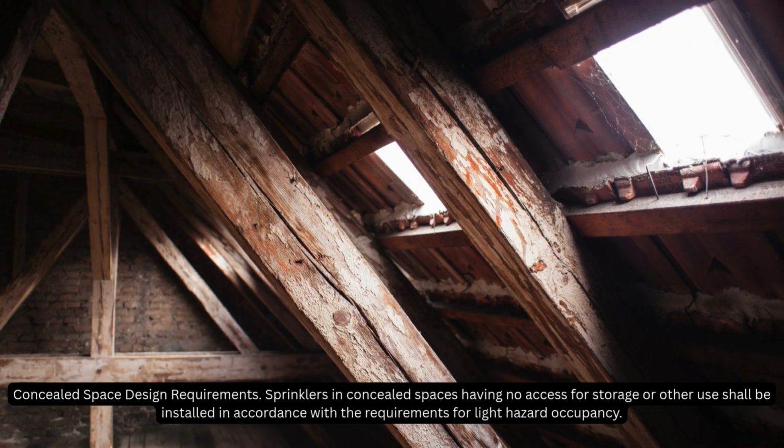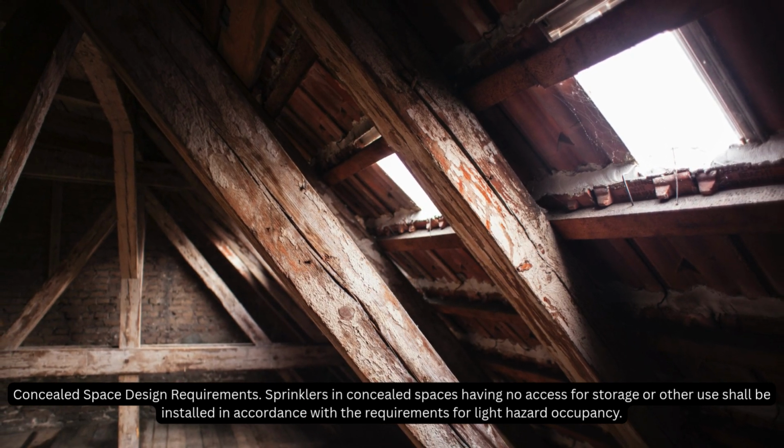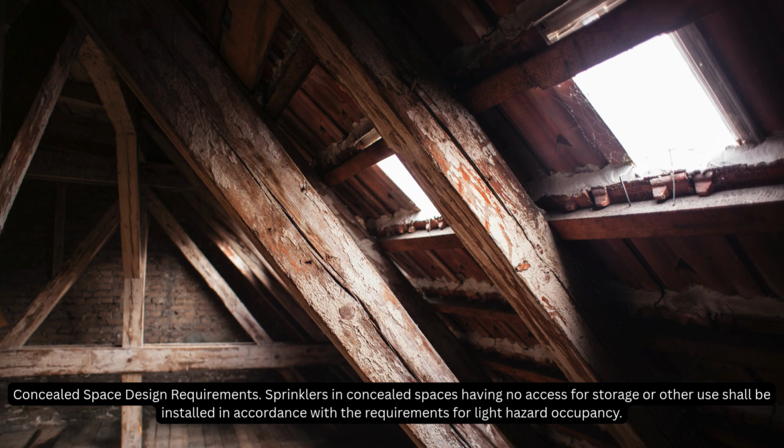Concealed space design requirements. Sprinklers in concealed spaces having no access for storage or other use shall be installed in accordance with the requirements for light hazard occupancy. Now let us move on to ordinary hazards.